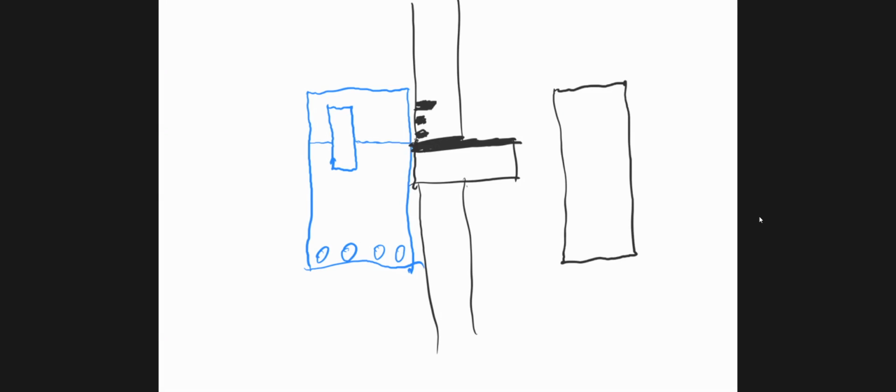If you're too low, you'll see two large arrows, or three large arrows down here. I'm only going to draw two. It's an LCD screen, so these are dark gray against a light gray background, okay? And you'll hear a quick beep, beep, beep, beep, beep, beep. As you raise the receiver up, these arrows disappear as you get closer to being level.